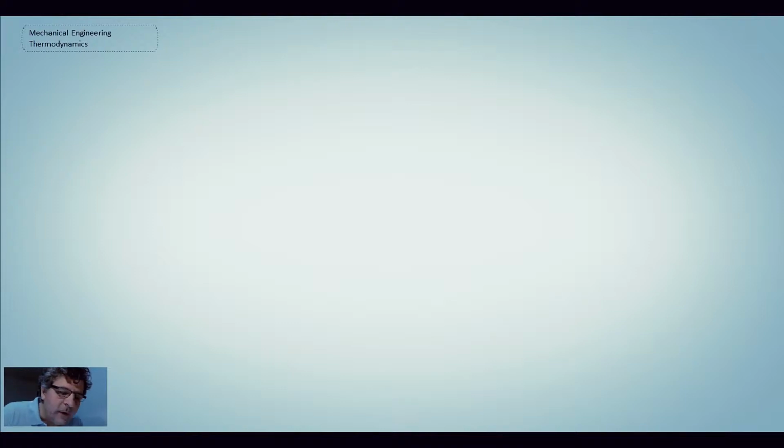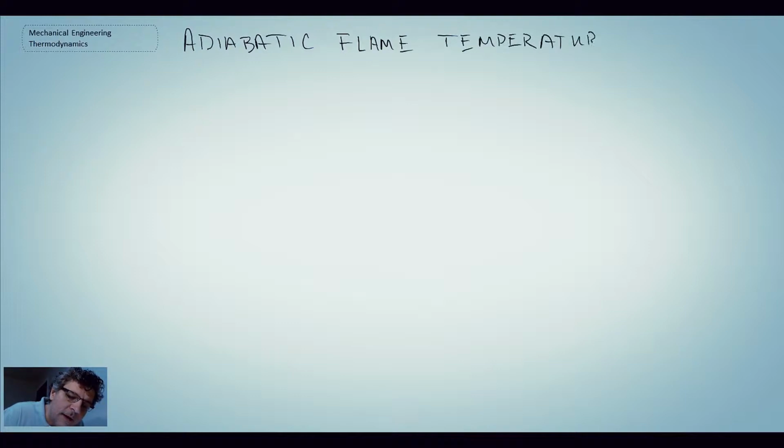In this class, we're going to take a look at a concept or topic called the adiabatic flame temperature. This is the maximum temperature that you would be able to get in a combustion process. It enables an engineer to calculate the max temperature that they may encounter for selecting materials or any other thing like that.